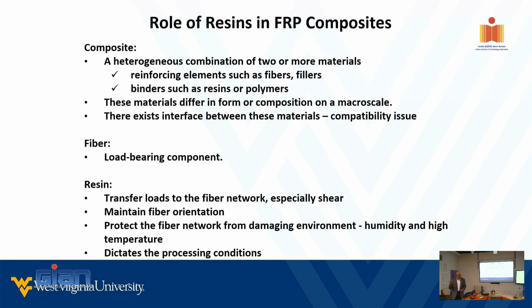I can throw the chemical names. They may not mean much to you, but I'll still throw the name so at least you have an idea. But the message is this: without a sizing or a coating on the fiber, you will not have proper binding or bonding between the fiber and the resin.